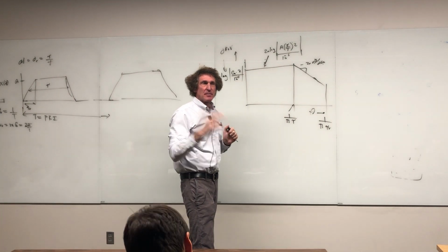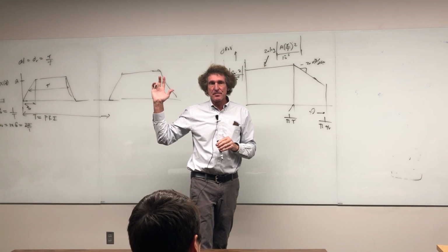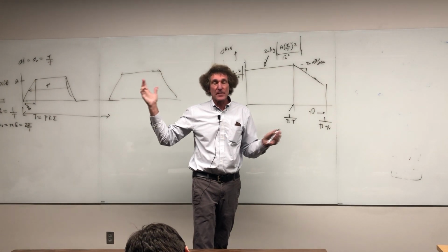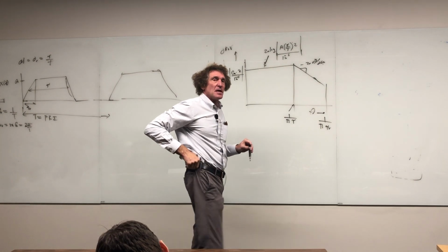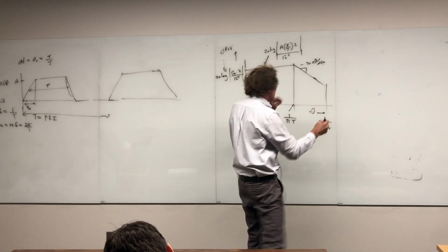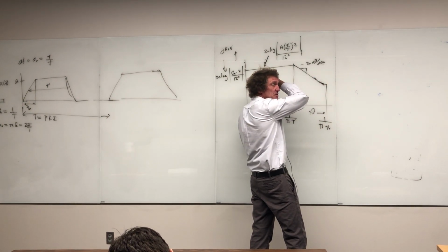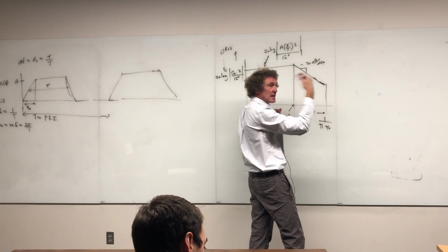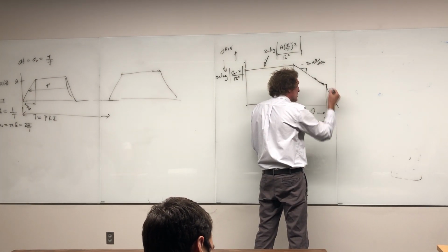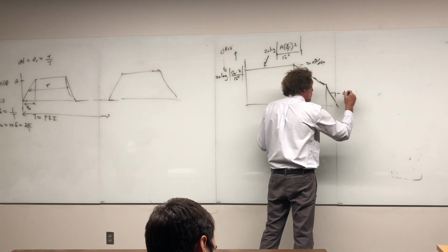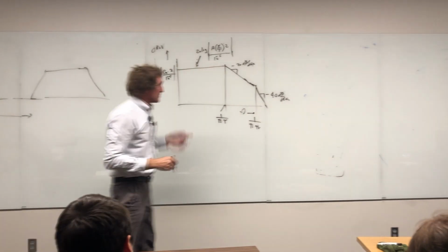How many have seen a spectrum analyzer or a network analyzer being used? Do any of your laboratories use this or not? Radio lab, perfect. So you at least know what I'm talking about when I'm talking about sweeping the frequency and looking at that curve. This is the typical way you do EMC analysis. This is actually the signature of, if you took the frequency spectrum of that signal generator, this would be the envelope. Then after this frequency, it starts going down at minus 40 dB per decade. All right? So there's the first and the second.